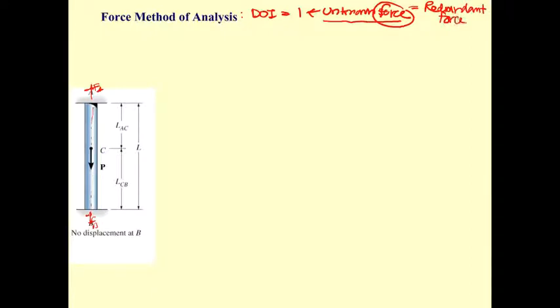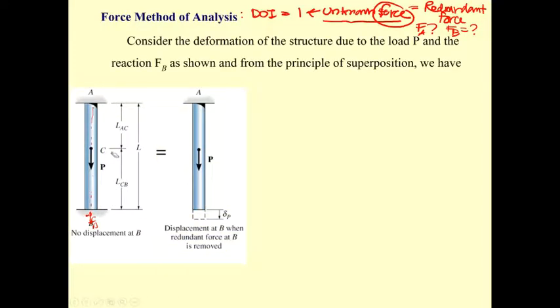force. That means we have more force, redundant force, and you decide whether you're going to use F sub A or F sub B. If you use F sub B, your structure will change to this: the structure will be subjected to P and F sub B. And now you may use the principle of superposition.